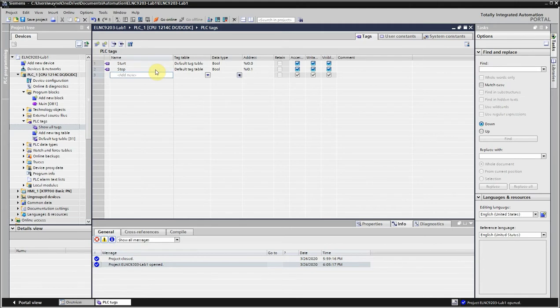It'll come up as I0.1, then auto, manual, reset. Okay, now at this point, I want to type in two tags for my outputs. One was going to be on, and Q0.1 was going to be auto mode. So I'm going to type in on. Now you notice it came up as I0.5, so I can go over here and override this and just go ahead and type in Q0.0.